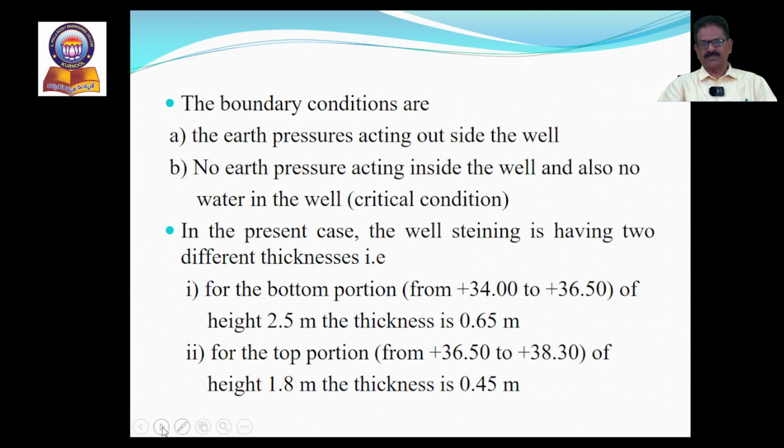So what are the boundary conditions? Let us consider the boundary conditions for the present case. As already explained, there are two. One is the earth pressure acting outside the well. Completely on the outside of the well, the radial earth pressure is acting, and the intensities of these earth pressures are already calculated. Whereas inside the well, there is no earth pressure acting, obviously. And since the well is empty, we consider no water in the well. That is the critical condition.